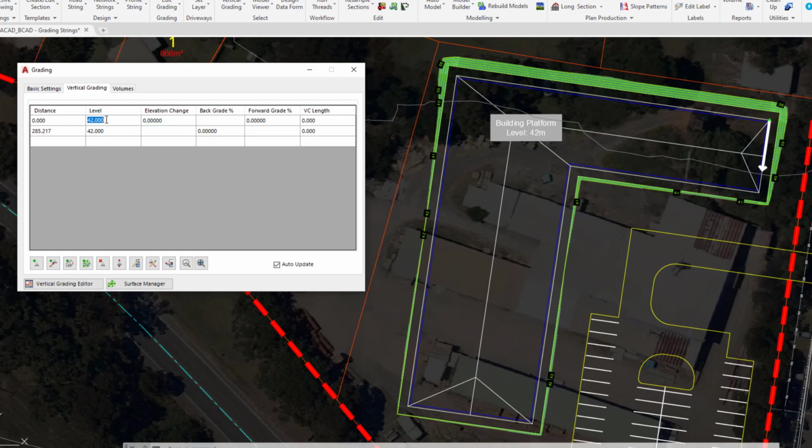The cells that we have within the form are editable, so if we wanted to go in and make a change we could do. What we're going to do is look at how we can add elevations along our polyline at different points of our choosing. So to do this, we're going to find the first button on the bottom left hand corner of the form, which is Add IP by selecting in the drawing. Go ahead and click on that button.